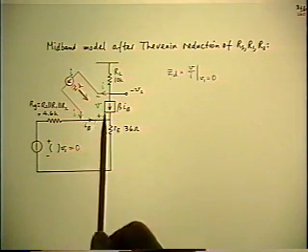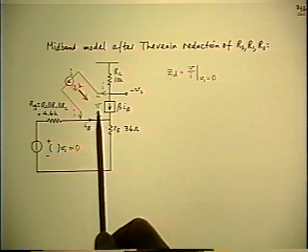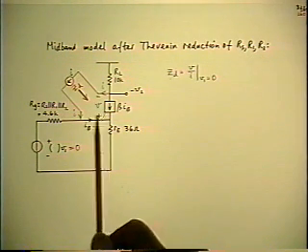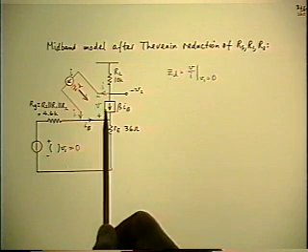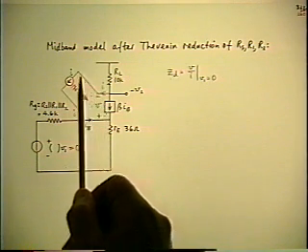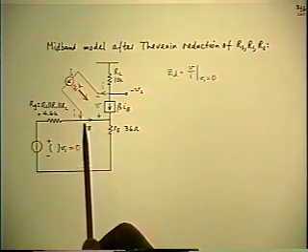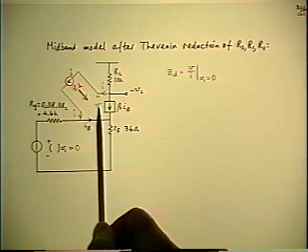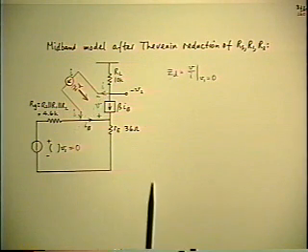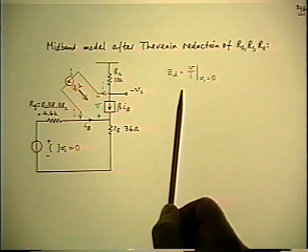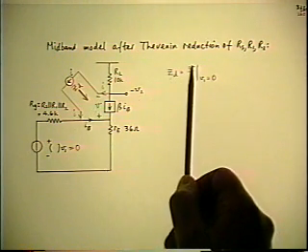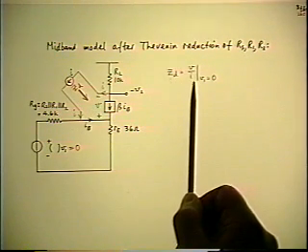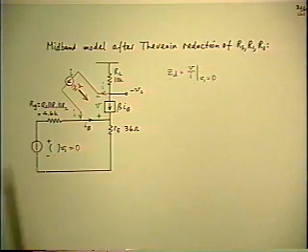This means we actually have to back up a little bit and do a real calculation. So what is it we're trying to find? I've identified the current I which is being driven into these two terminals, and the V is the resulting voltage. And the answer we're looking for is the green V divided by the green I under the conditions of 0 V1.